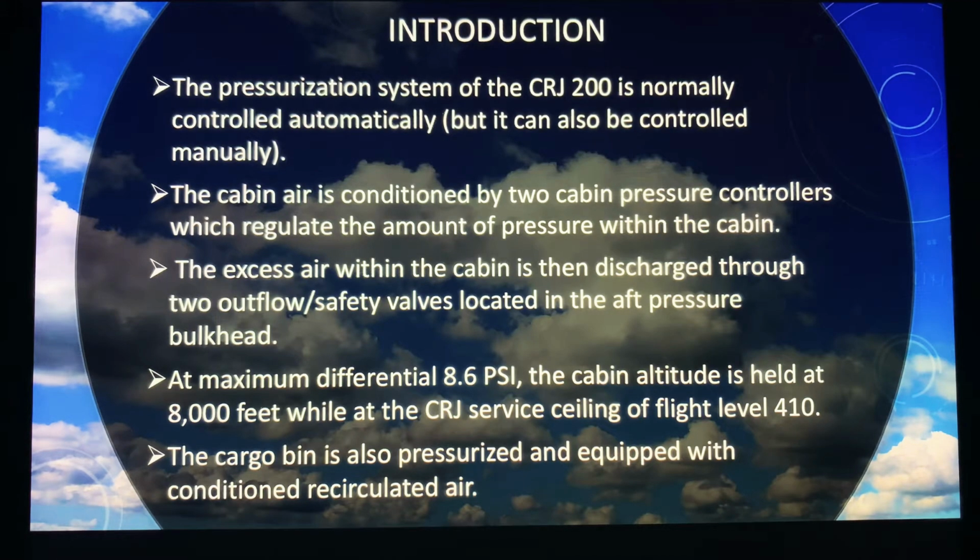At the maximum differential of 8.6 psi, the cabin altitude is held at 8,000 feet at the CRJ's service ceiling of flight level 410. The cargo bin is also pressurized and equipped with conditioned recirculated air.